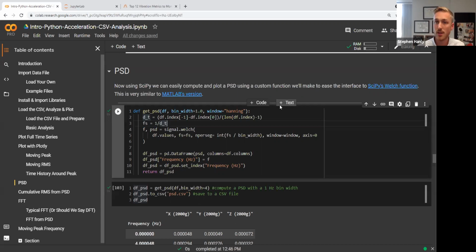We can look into adding some other functions to, like, find the peak, but you kind of saw my example. The other thing in our library for the shock response spectrum, we have a function to find the equivalent half sine pulse. So you have really complex acceleration data, and maybe you just want to simplify it into, well, what is the equivalent amount of energy in just a simple half sine pulse? There's a function to give you that result. And we're actually giving a paper, Becker is, and a talk. That might be its own webinar and blog.